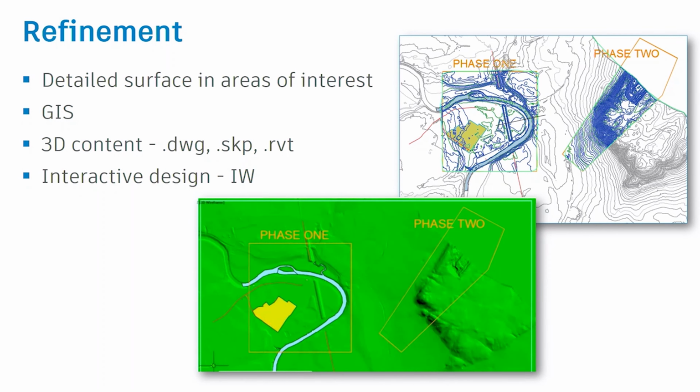Okay, what's the largest size in point number that a Civil 3D surface should be? What's the maximum? Civil 3D Jeopardy. The maximum number of points in a Civil 3D surface. 2 million. Okay, so when you start to get more than 2 million points, it actually starts happening at like 1.8. It caches out, and you can have huge surfaces. It just caches out to a memory mapped surface file, and you want to kind of avoid those at all costs.